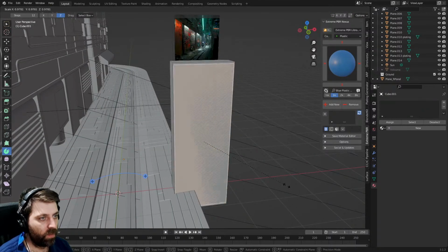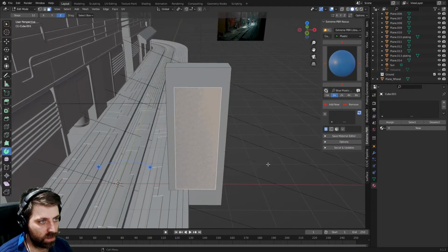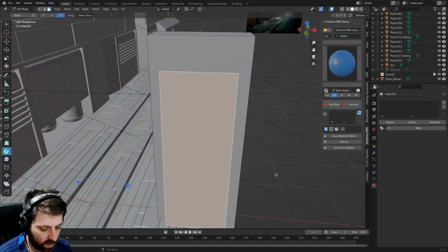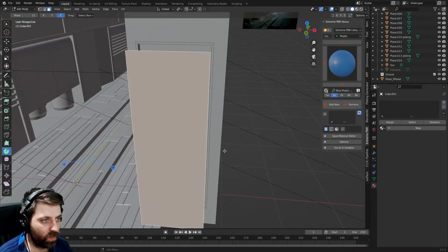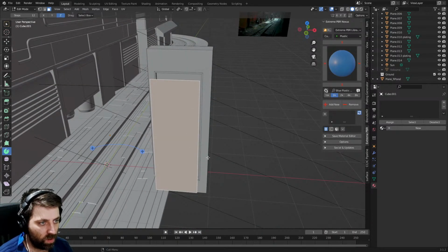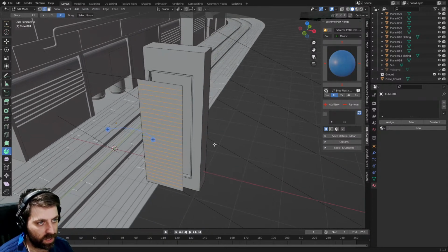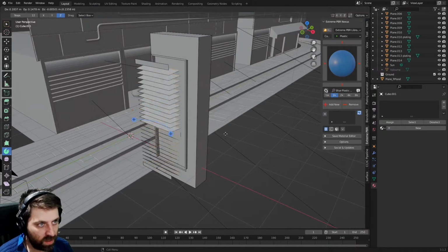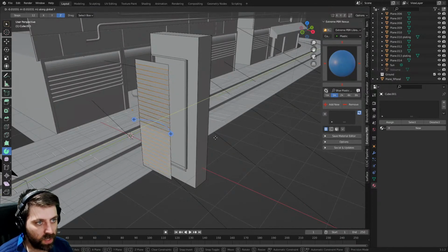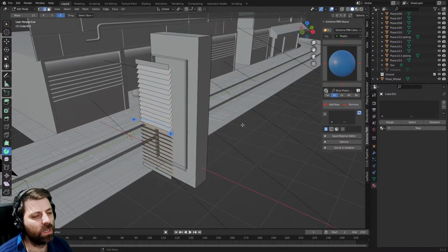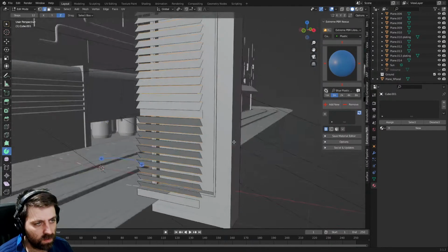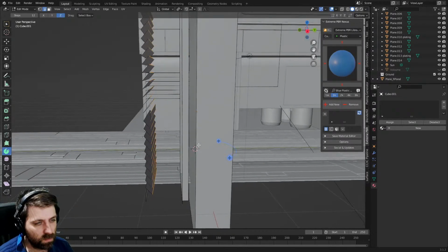So let's go ahead and maybe we'll do an inset, scale, GY. Let's do I to do an inset, E to extrude, Shift D, GY, bring that out. From here, I'm going to put in a whole bunch of edge loops. Okay. Let's press V to rip, GY to bring it out. Actually, we'll go in. Oh, don't be a jerk. You suck.